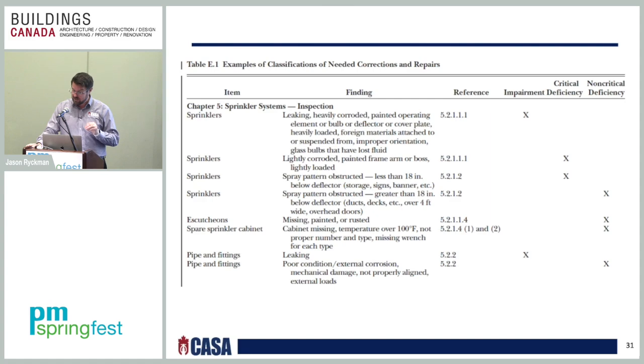It also states that sprinkler systems shall not be used to support anything that will interfere with effective sprinkler system performance. So that's going outside the scope of NFPA 25, because with NFPA 25, remember, we assume that the design and installation is done correctly. And this ultimately becomes the fire code telling you that you have to do it. So it's very interesting. I just want to bring that up.